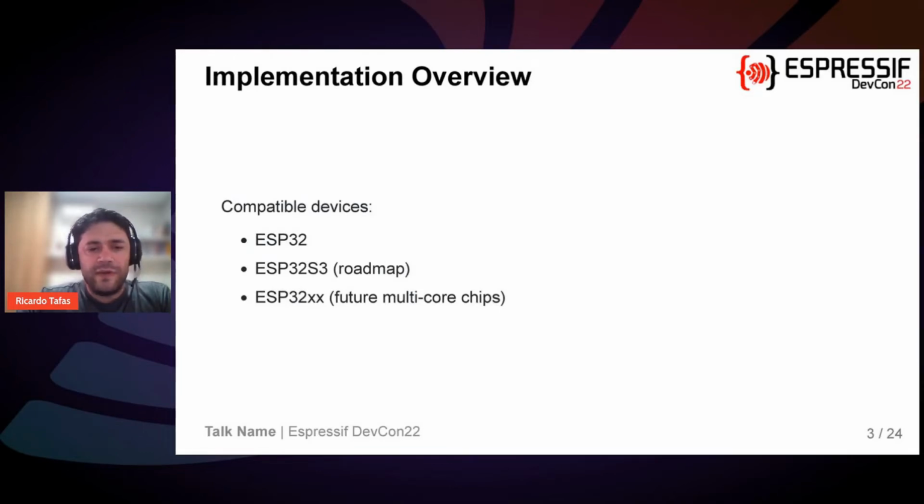So before we start, AMP, as we expect everyone to know, is asymmetric multiprocessing, which happens when we have two different CPU cores, or the same core that work in a different way. For example, on ESP32, we have the same core, but they behave a little bit differently in the way we understand and use these cores. So we can consider that as asymmetric multiprocessing.